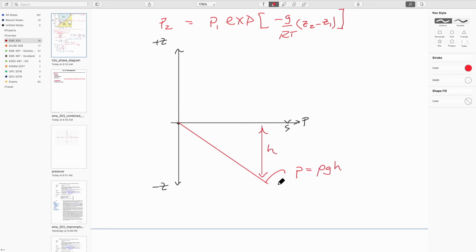Right? This is linear. This is the density of water, if we're thinking of this as being a liquid. This would be gauge pressure, if I'm spelling that right. I think I'm not. So this would be 0, if that's 0 gauge. And that's what we're feeling here. But of course, this is actually equivalent to 101 kPa absolute.